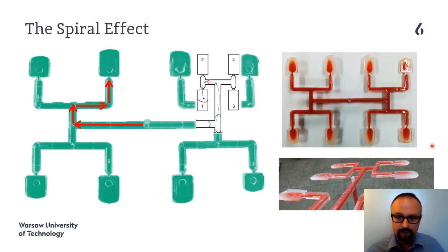As we can see here, this more viscous material tends to stick to the core of our runner and fills the outer cavities faster, and this less viscous one, this transparent one, is situated more closely to the walls of the runners and fills the inner cavity first, and it also fills the inner side of the inner cavity in a faster manner.